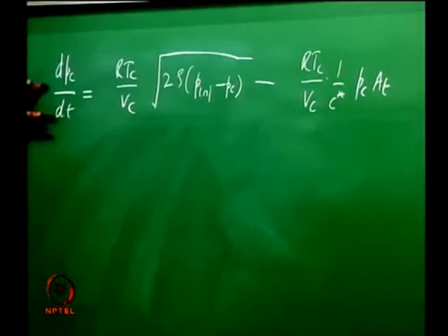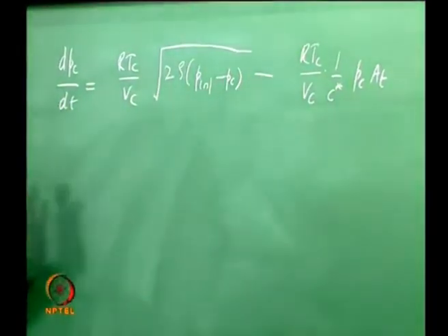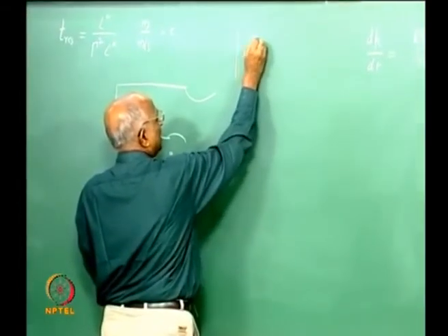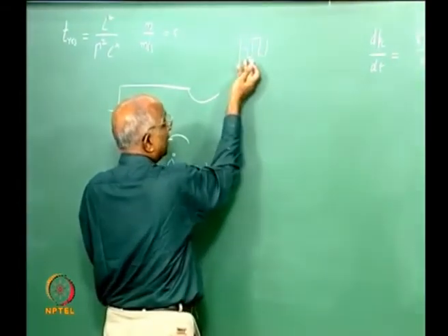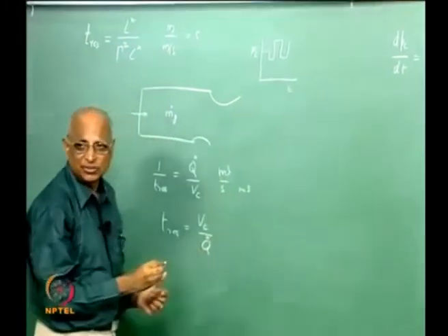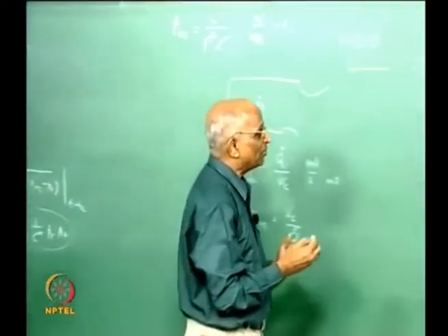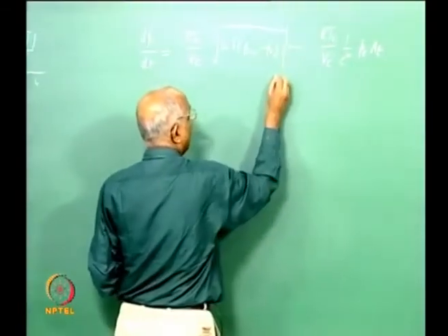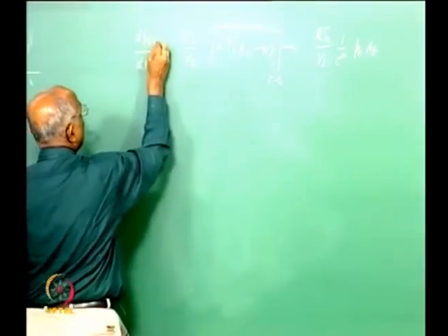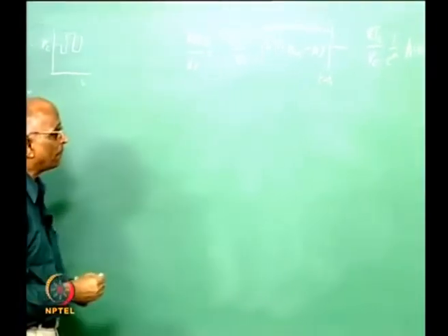Essentially what is it we are looking at? We are looking at the variation of Pc with time. Whatever we studied just now with the numerical example, we found that under some conditions it goes like this. What is the rate at which pressure changes with respect to time is what we want to predict using this equation, and precisely that is what I am solving for. But we also note something here, which is very primary: this happens T minus Tc before this, therefore this is a function of time, and Pc is also at time t over there.